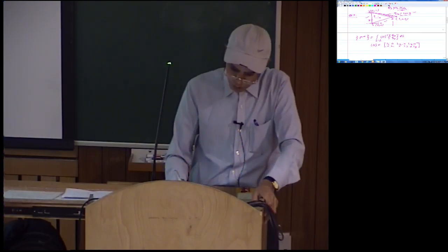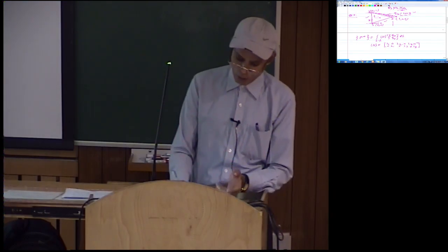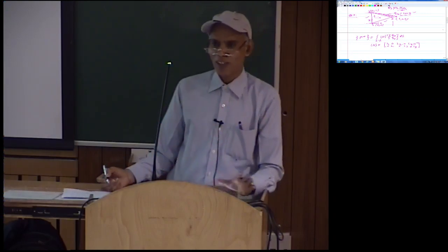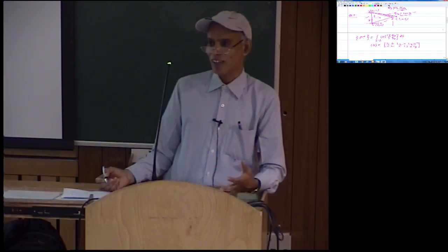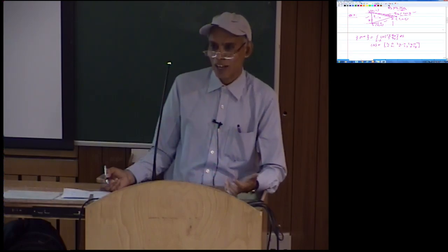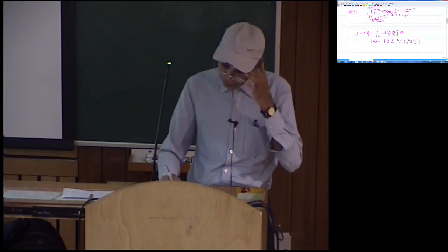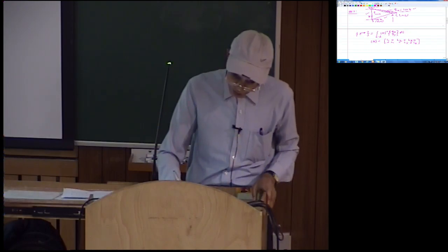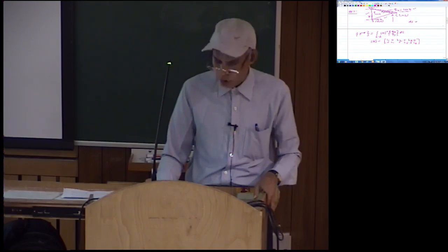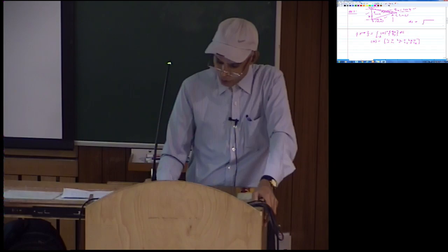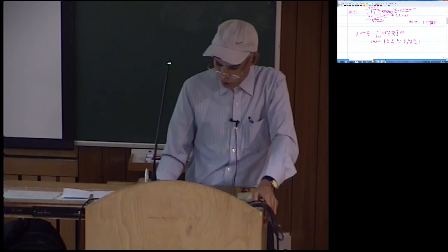Now that integration is going to be along the edge. Again, some of you just tried to write it as a double integral, because when you go either 3 to 2 or 2 to 3, x and y both are changing. See, the load is acting along an edge, so it has to be a line integral, it can't be an area integral. So if you are going from 2 to 3 the way we discussed, you have to take a ds here, and that ds is going to be of course the square root of dx square plus dy square. You can take one of them out, say dy by dx whole square, and then dx.